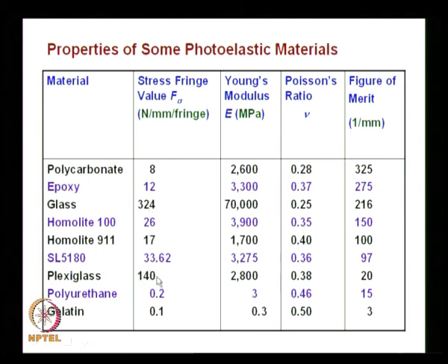it is about 140, and polyurethane, which I said that I can even apply loads with the finger, has a very low F sigma of the order of 0.2, and its Young's modulus is also very small, it is only 3 MPa, whereas for all the other plastics it is about 3 GPa, and glass is almost like aluminum, it is 70 GPa.